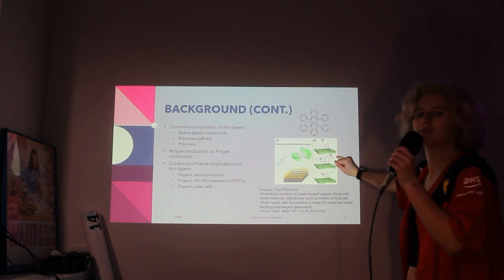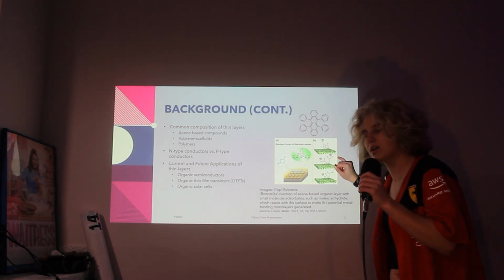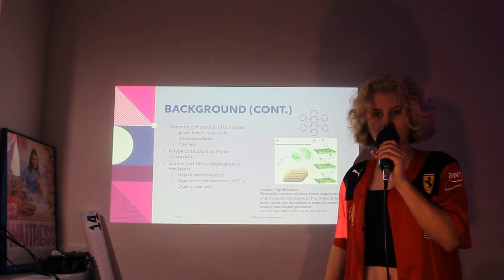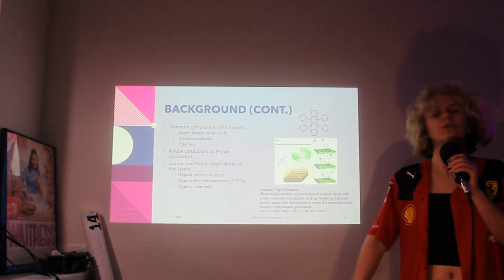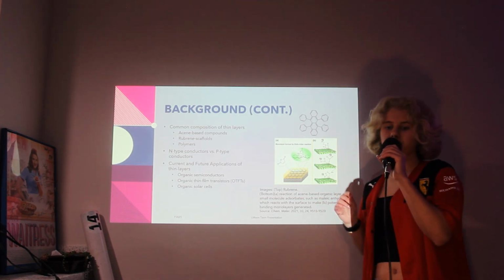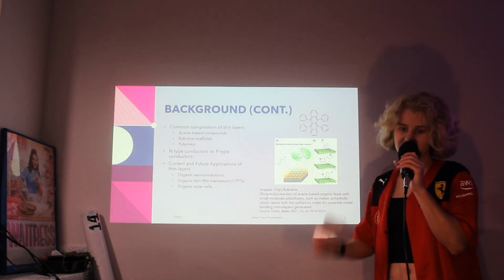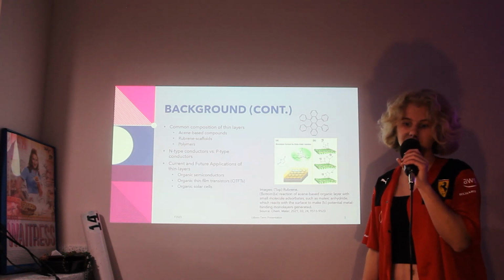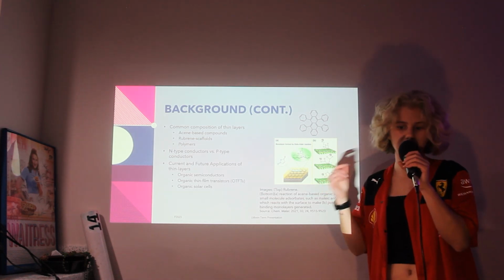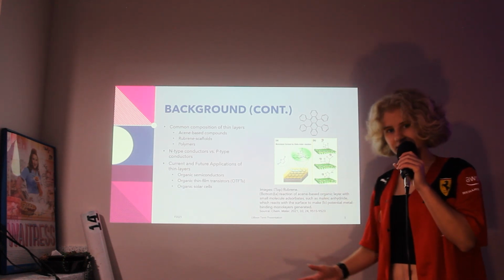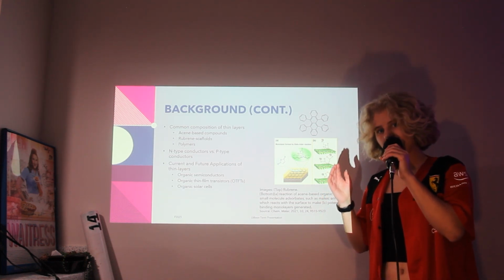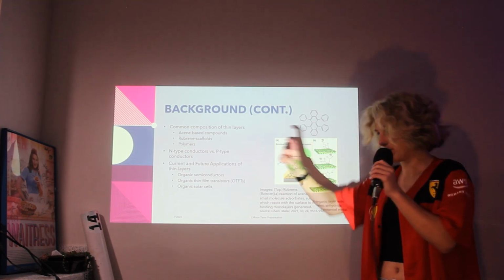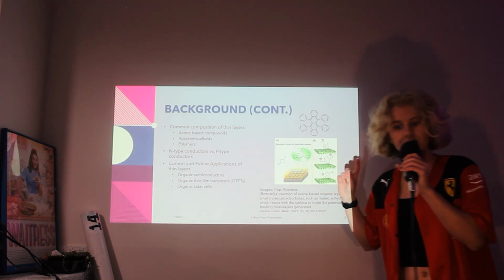metal layer, and then also that increases the conductivity of the material because those atoms are more electronegative than carbon. So you can add electron donating or withdrawing groups to the system, which increases the conductivity by increasing the mobility of electrons in the conduction layer or the mobility of holes within the valence layer. This is actually necessary in order to make an organic semiconductor. Otherwise, it would act more like an insulator because that band gap is so wide. So they have to dope it.